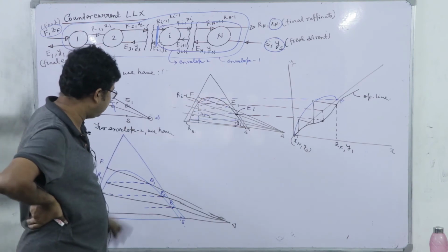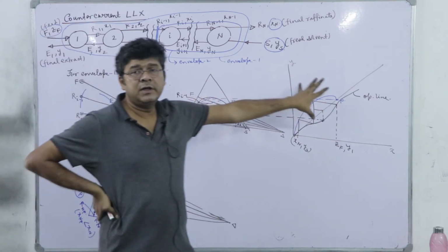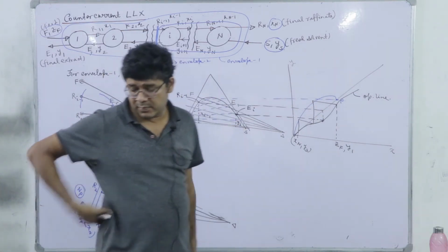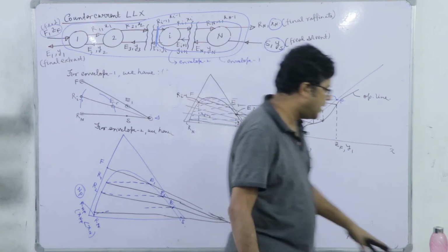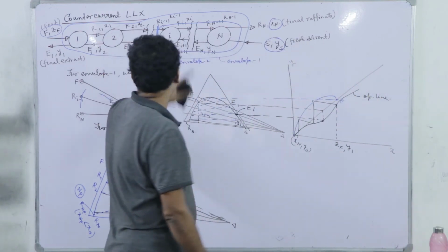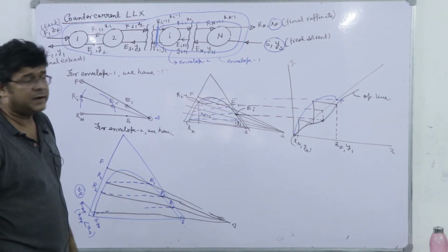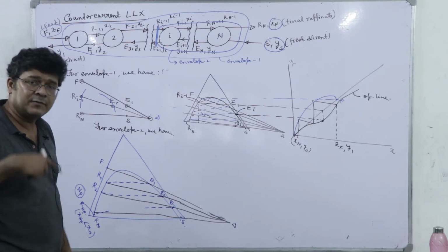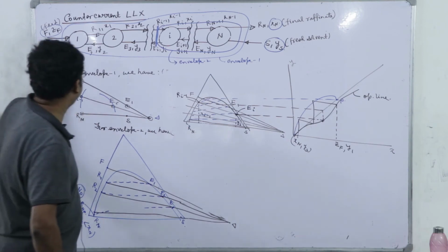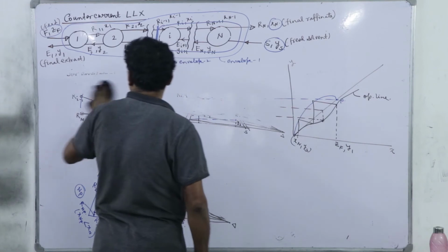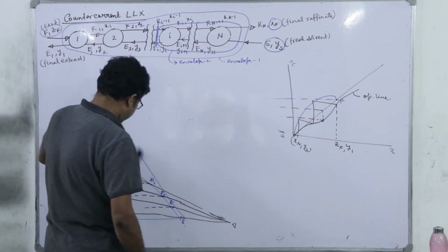From there we can simply calculate what will be my number of stages. What we were doing by tedious graphical construction, we can simplify, though the initial construction will be much more, as we have to construct this y versus x space. So, that is about the countercurrent extraction, but here lies a problem. The problem is the solvent flow rate will not be provided. So, very similar to all these previous mass exchangers, we have to calculate the minimum solvent flow rate.